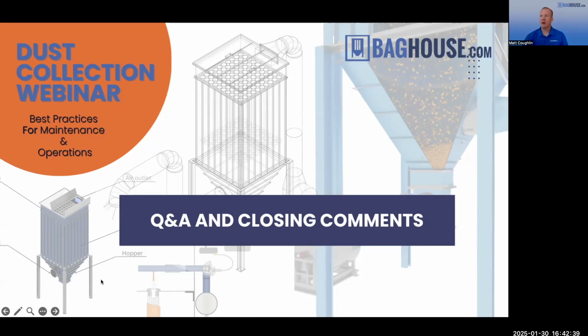Can I add, Dominic, just one or two quick other things? On that point, most of the timer boards that come along with your baghouse in this day and age will have a differential pressure readout, like a digital readout. And it's important to make sure that you're getting good readings. The way those work is very simple. It's just two air tubes. But if they get blocked up or the tube cracks and you get an air leak, your differential pressure reading, which is your most fundamental baghouse health measure, may not be reading correctly.